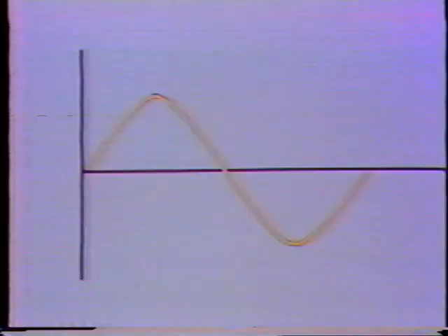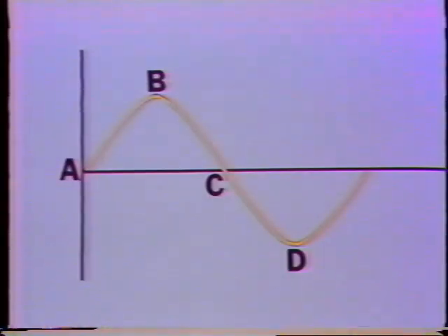Okay, now on this single-phase motor, we have a permanent magnet for a rotor. These wires or windings around the stator make it an electromagnet. What we want to see really is the interaction between the rotor and the stator, the two magnetic fields. We can show the effects of this interaction here in the form of a sine wave. We've divided the sine wave into 5 sections: A, B, C, D, and E. Now we're going to apply alternating current to the stator.